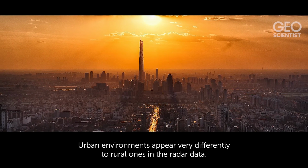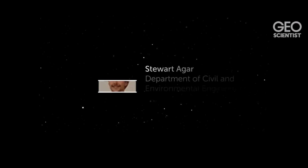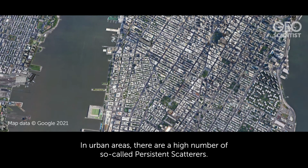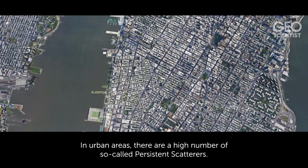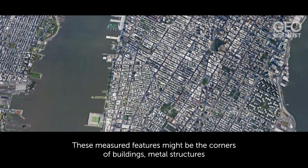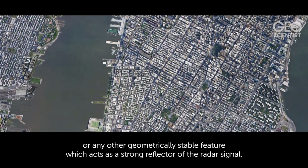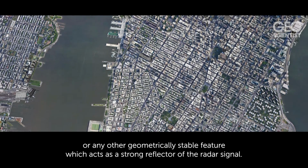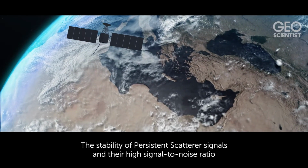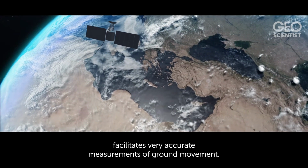Urban environments appear very differently to rural ones in the radar data. In urban areas, there are a high number of so-called persistent scatterers. These measured features might be the corners of buildings, metal structures, or any other geometrically stable feature, which acts as a strong reflector of the radar signal. The stability of persistent scatterer signals and their high signal-to-noise ratio facilitates very accurate measurements of ground movement.